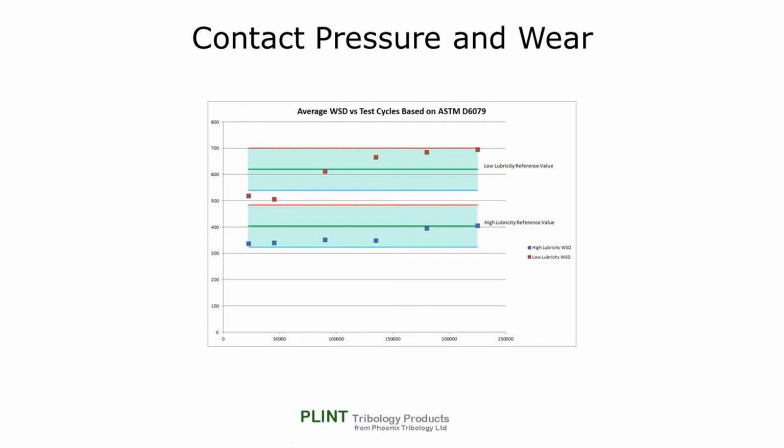It would appear that an acceptable result can be achieved within the limits of the standard, running tests at any frequency from 20 to 50 Hz. It would appear that the choice of frequency and number of cycles is pretty much arbitrary, and that comparative results could be achieved with much shorter tests.